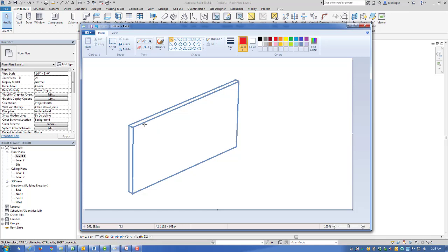Well, we know the studs are going to be either 2x4s or 2x6 at 16 or 24 inches on center or whatever. We actually don't need to come in and draw them because that would take forever. Well, or do we want to? Well, you know the answer. It depends. What does it depend on? It depends if we want to schedule or know things about the studs.